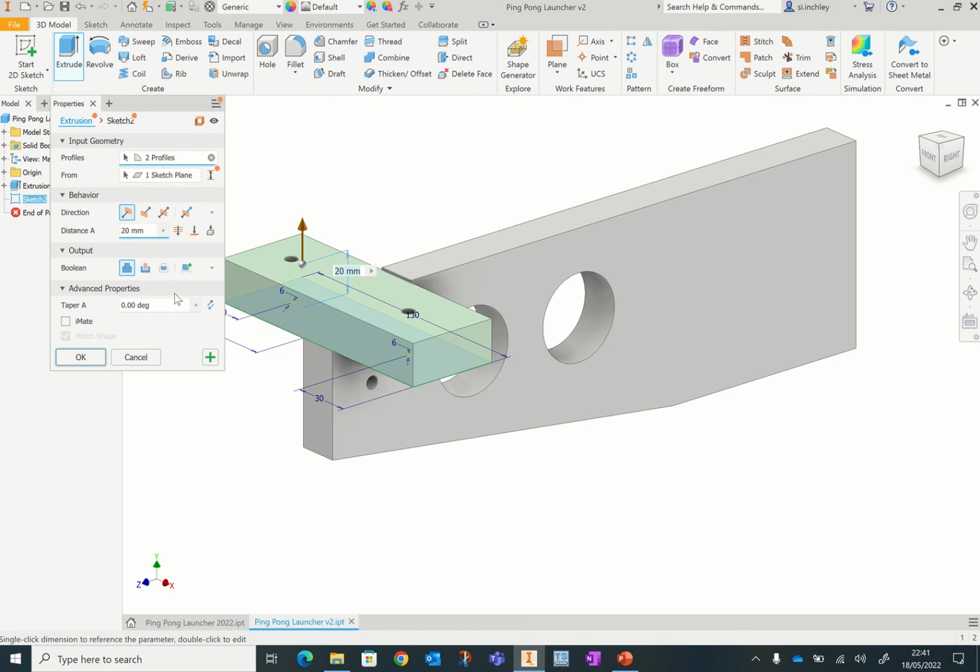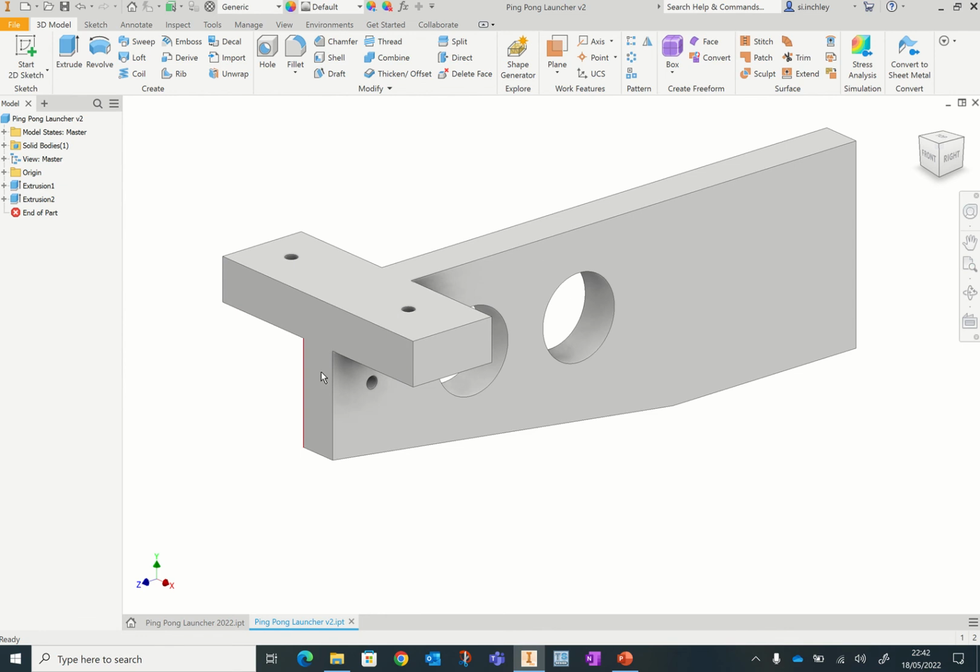All right, and you can extrude that. We're going to extrude that by 21 to bring it up to the top. Now this is really important that you press this button here called New Solid. That makes sure that it is a completely separate part. I'll show you what happens if you don't click that button. If you just click OK, see how it just joins to this material completely. It's not a separate piece.